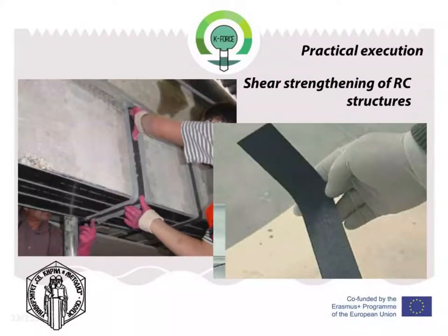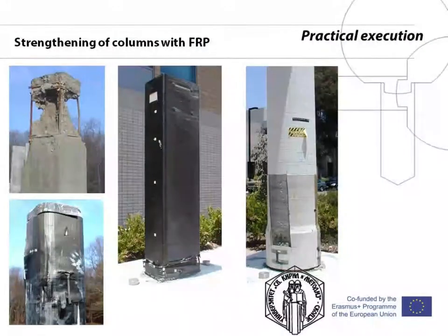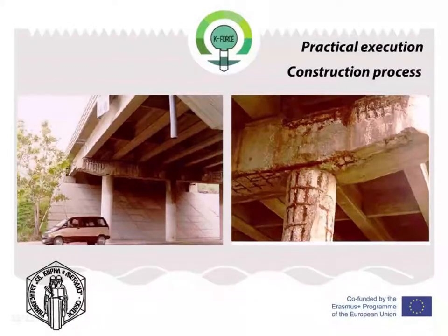The following aspects should be considered. The minimum concrete tensile strength should be greater than 1.5 Newton per millimeter squared. If the damaged concrete has reached a depth that no longer allows shallow surface repair, replacement of the concrete should be considered. Corrosion of the internal reinforcement should be stopped to avoid damage to the concrete due to expansive rust. Repair or protection is needed if the steel is already corroded or is likely to start corroding.